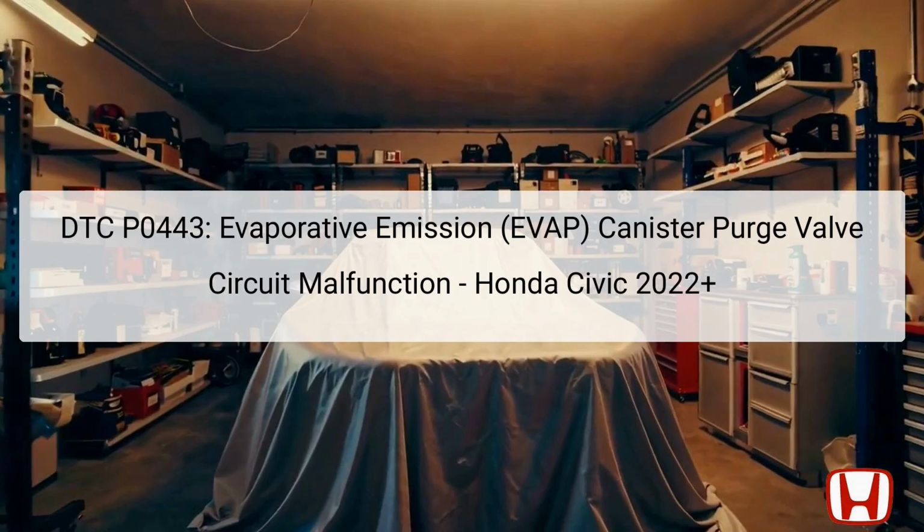When the PCM, or powertrain control module, detects that the return signal from the valve does not align with the expected output signal, it sets the P0443 code. This can happen due to issues in the valve itself, the surrounding circuitry, or the PCM. The diagnostic process consists of several systematic inspection steps to identify the faults leading to this DTC.